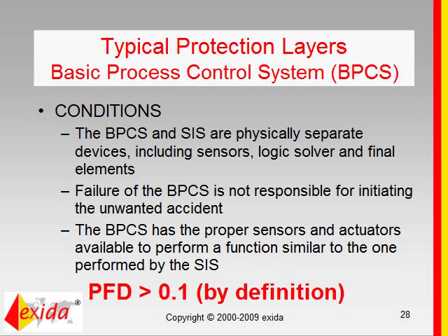Another question here is who normally facilitates the layer of protection analysis meeting? Is it normally done by the end user? Can it be done by the design engineer, or is it a third party? Arguably, the answer to this question is yes. It all depends on how you structure your project, and that is part of your functional safety management that you need to implement as part of 61511 compliance.